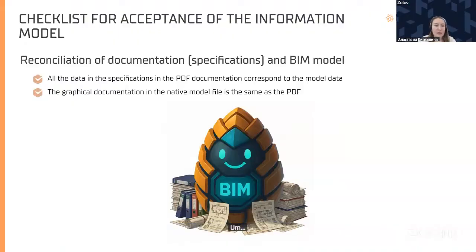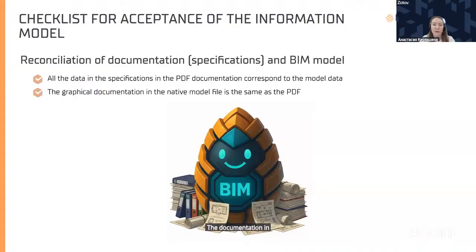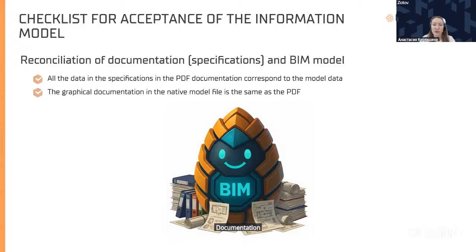The next step is reconciliation of documentation and the BIM model. It's vital because sometimes the documentation and the BIM model are separate things. Firstly, the designer does the documentation, and only later makes a model, and the documentation doesn't match this BIM model, and it's a problem.